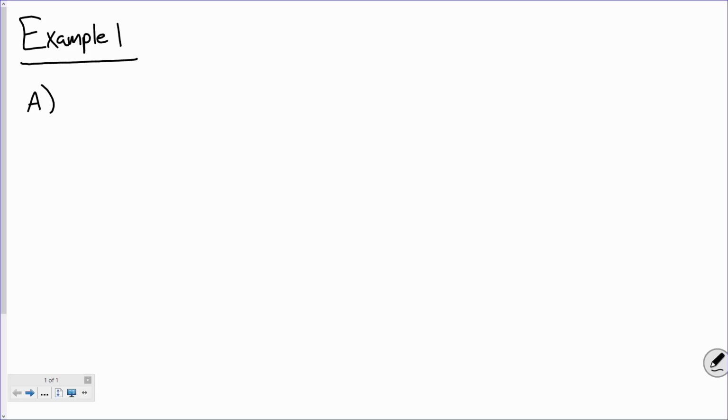Well, let's just go back to the mechanics. The mechanics says that we have a bending stress profile that looks something like that. And we calculate our stress as M y over I, right? Everybody good? Okay, a little bit of a review. We need to calculate the moment of inertia. How do we calculate the moment of inertia of a rectangle? There we go: b h cubed over 12.